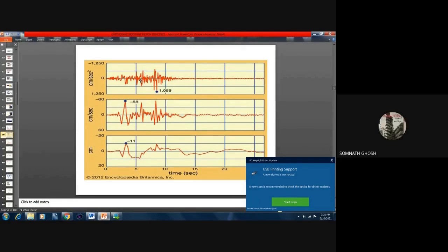So we try to measure this during an earthquake by implanting instruments at different levels from ground level in the soil, and we continuously get the response from those instruments, which we record in the computer. Later on, people use it for analysis. And these kinds of systems are extensively used in IIT Roorkee.